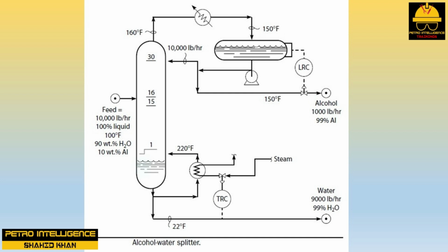An increase in reflux rate, assuming that the reboiler is on automatic temperature control, increases both the tray loading and the vapor velocity through the tray deck. This increases both the total tray pressure drop and the height of liquid in the tray's downcomer. Increasing reflux rates, with the reboiler on automatic temperature control, will always push the tray closer to or even beyond the point of incipient flood.